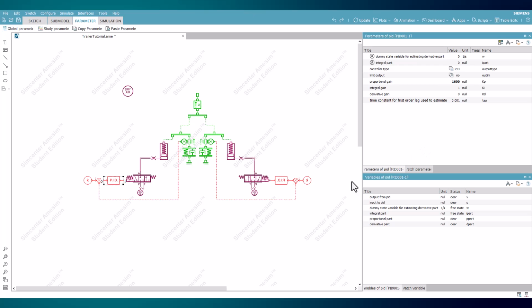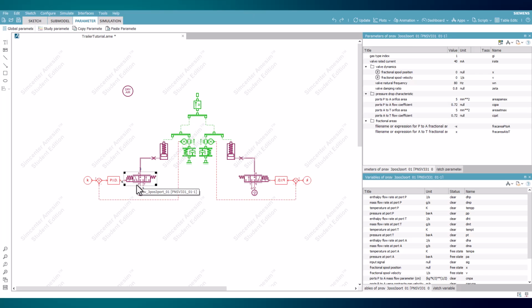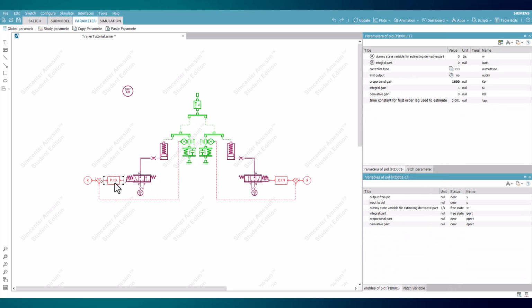The sign of this value must be evaluated as well, where a positive 40 milliamps moves the valve to position 1, where the port for atmospheric conditions is opened. Negative 40 milliamps moves the valve to open the pressure source, which is the desired action at maximum error, meaning the proportional gain should be negative 1600.